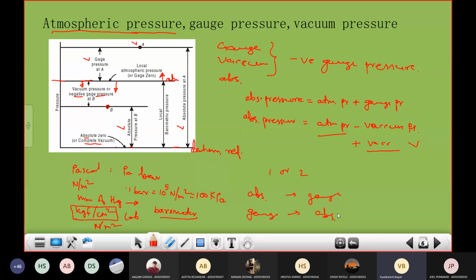Yes, sir. Okay, fine. One more thing I should mention before we proceed. As I said, in case of laboratory gauges, when the pressure you measure is above the atmospheric pressure, you will see this type of unit used, kgf per centimeter square. And whenever you are measuring the vacuum pressure using the laboratory gauge, you will see the scale which reads mm of Hg instead of kgf per centimeter square, as the vacuum pressures are less compared to the gauge pressures.